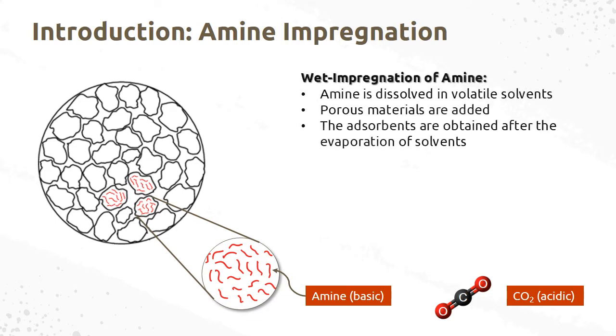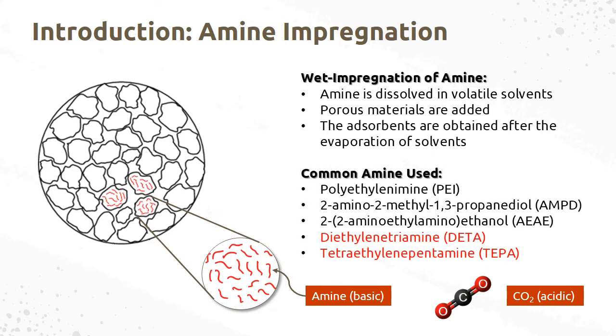Wet impregnation is the most common method used to prepare the amine-impregnated adsorbent. Polyethylenimine (PEI) is the most common amine used out there, but in my paper, I employ diethylenetriamine (DETA) and tetraethylenepentamine (TEPA) for CMS amine impregnation.